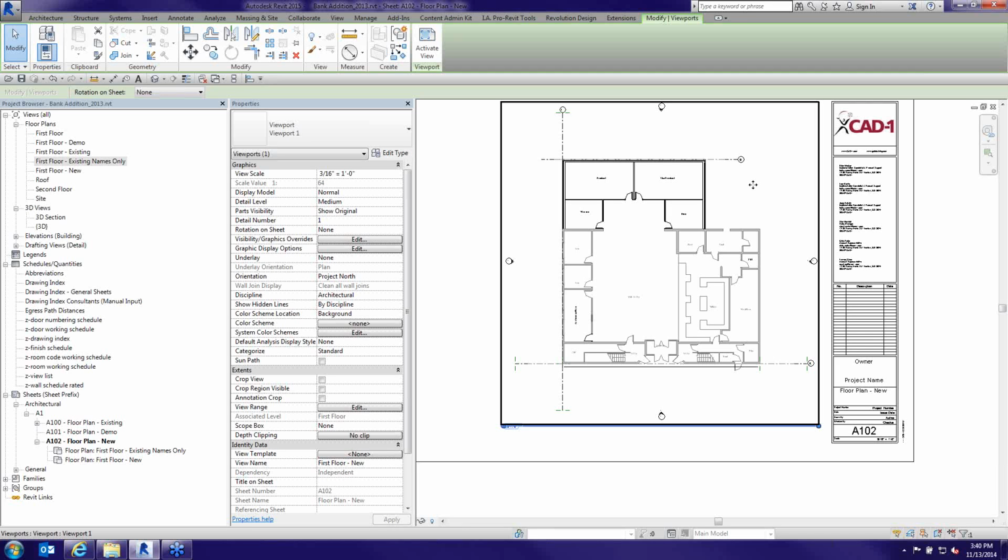You try to add new portions to it. So I'll let you guys discuss this with your Revit MEP people, but if you're doing a project that's using phasing, understand that it is difficult for the mechanical side and the plumbing side to tap into existing things and to do those calculations. So make sure you sit down with your mechanical engineers and say, okay, we're going to do phasing. Here's what we were thinking. Let's talk this through so we can make sure we see what's going on in there as well.